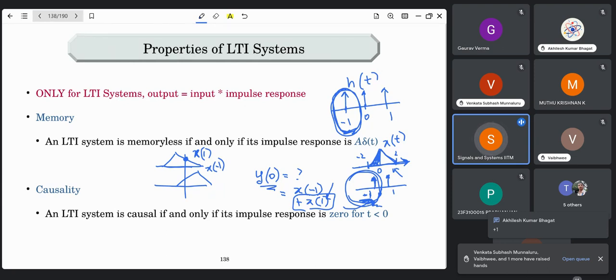Whenever you feed in noise, the noise at the input is random, the noise at the output is random. But the way the system processes this noise is deterministic. The characteristic of the system is deterministic, which means that the statistics of the noise get processed in a deterministic way. The input and output at a given point of time might be completely random, but the statistics like the mean and variance and their correlation are all processed in a deterministic fashion.